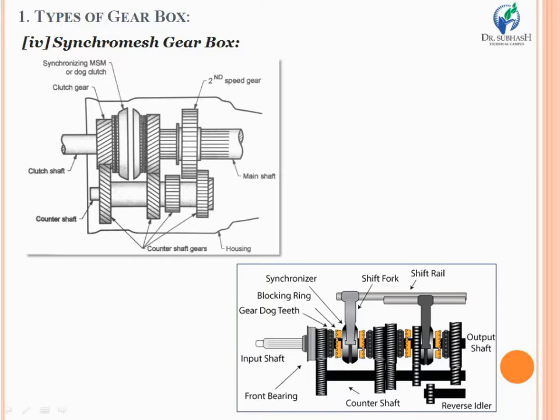Secondly, when helical gears are paired with helical gears, the pair has not line contact but point contact between them. So it reduces the pressure and force on the teeth. Ultimately it reduces the stress level produced on each and every tooth while transmitting motion and power.